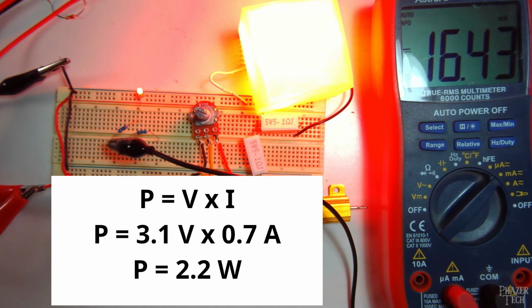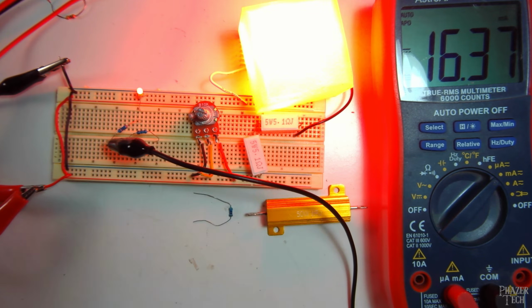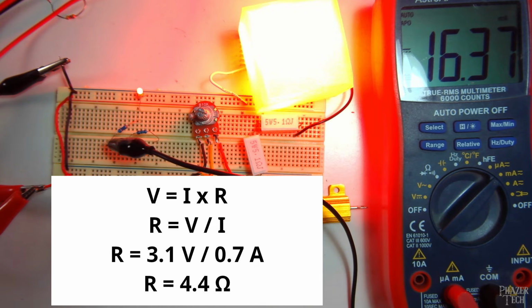This means that the resistor would only eat up about 2.2 watts instead of nearly 5 watts like it is now. But doing this also means you would need to change the resistor value in order to maintain 700 milliamps. So instead of using a 10 ohm resistor, we would need a resistor value of around 4.4 ohms to attain maximum brightness with a 5 volt power supply.